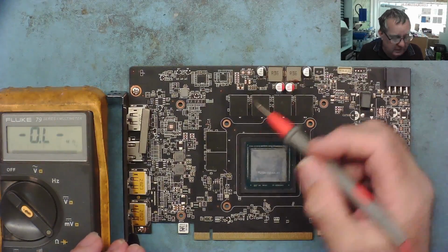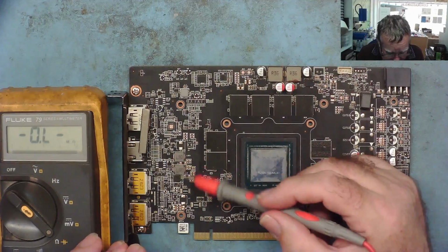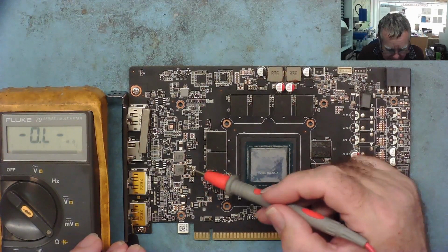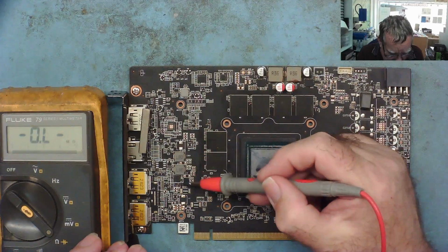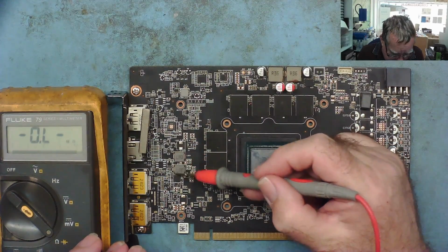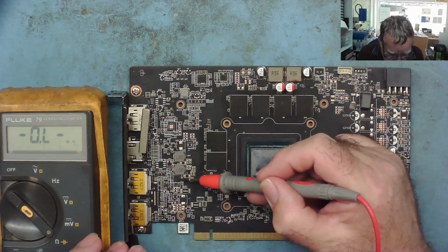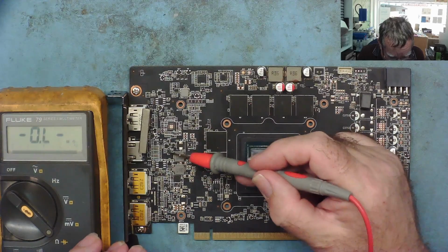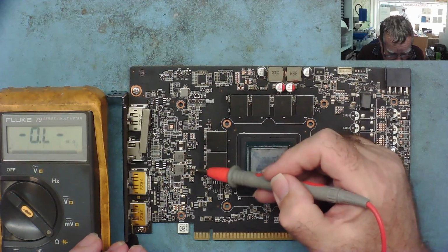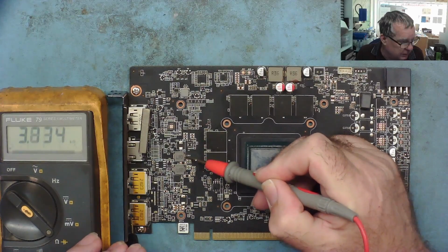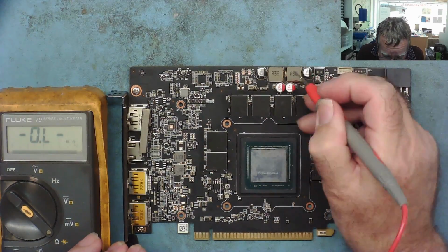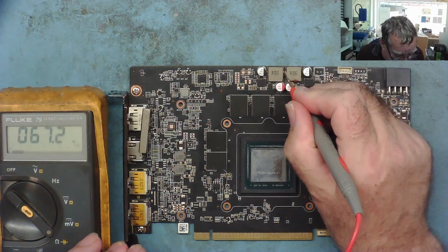If we're lucky, we'll find that the VRM which has the same resistance to ground as we're reading from here is one with a single phase like this one. So there's just one coil and one driver. Here's another coil and the driver's probably over here. We know they're only on a single phase because the resistance reads different on the two of them. These two up here actually both read the same.